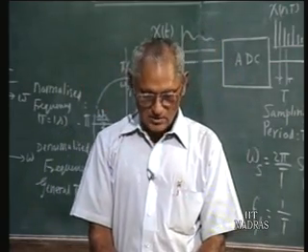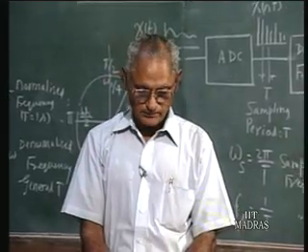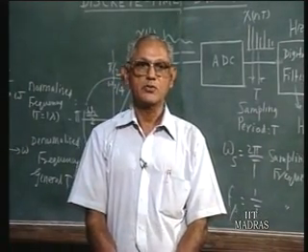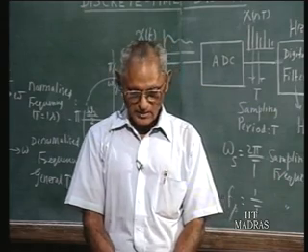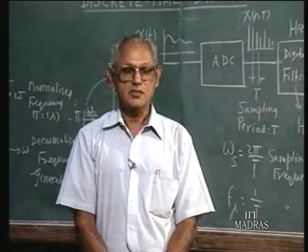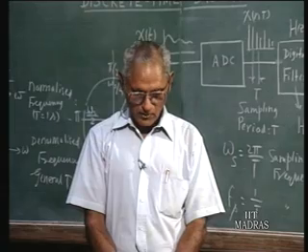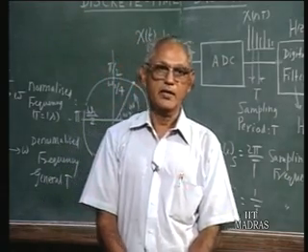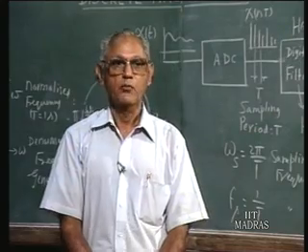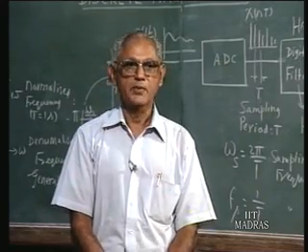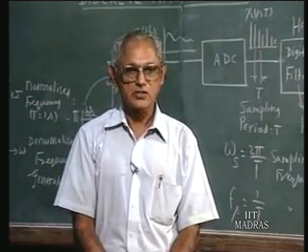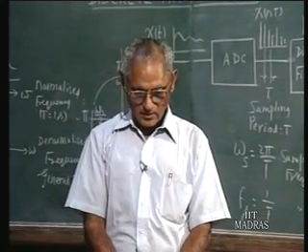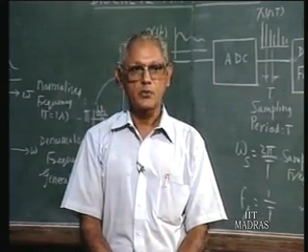And systems which operate on discrete time signals, which take an input sequence of these sample values and then produce a corresponding output, are called discrete time systems. Of the various kinds of discrete time systems that are possible, we confine our attention to the linear time invariant case, where the systems are described by linear difference equations with constant coefficients. And then we saw how to analyze these systems based on the difference equation approach.